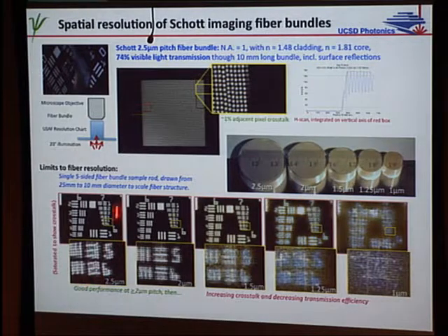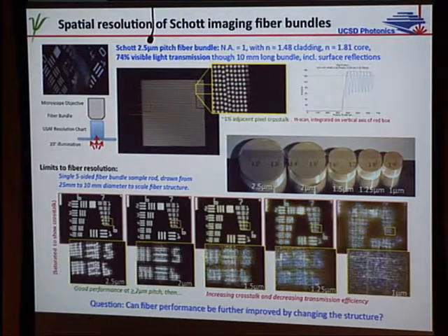And what you find is that the 2.5 micron bundle works great. This image is extremely saturated, actually. If you saw it in a linear domain, you wouldn't see anything that looks like crosstalk. And in fact, what may look like spreading is actually the light adjacent on 2 fiber cores. At 2 microns, you're starting to see a little real crosstalk. At 1.5 microns, it's got significant crosstalk. Below that, it's kind of a disaster. So that's with the standard fiber structure, and we want to improve that.